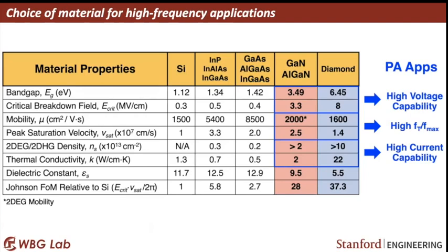We don't want that to happen, for which you need high thermal conductivity. If you have high thermal conductivity, the heat will dissipate properly. Diamond has a very high thermal conductivity. So these decide at what current you can operate your devices. That's also good for GaN, AlGaN, or diamond systems. That's one reason we go for these wide band gap materials for high frequency, high power applications.